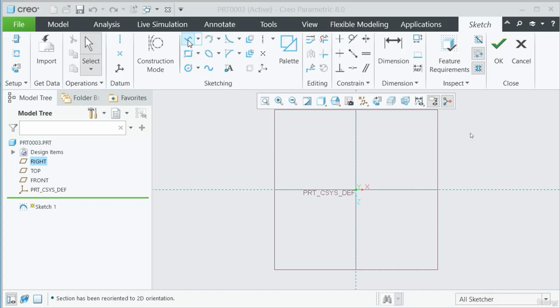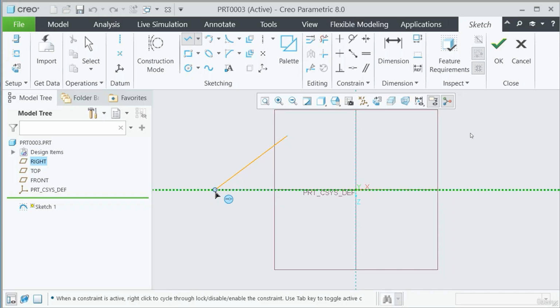This time, I'll select this line. In the last lecture, I have created 4 lines in a different shape. But in this lecture, we are going to discuss shortcuts for generating that rectangle. Let us select somewhere here. And as soon as I move down, you can see a vertical constraint is being given and the line is getting locked. You just have to move your mouse. You can see it is getting locked. Once it gets locked, when you click, automatically a vertical constraint is getting generated and the line becomes vertical.